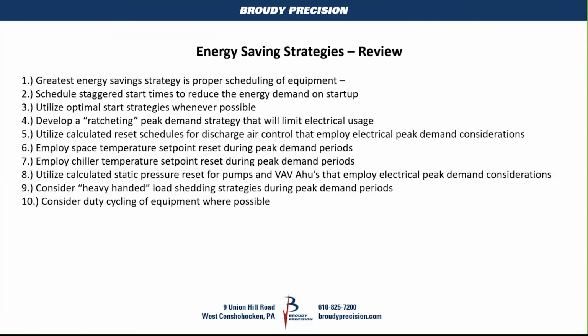We got time left here. So we start shedding loads, or we start changing the set points of air handlers, or we start doing things to reduce the energy consumption to keep it below 10,000. But then after our interval is over with, I want to go back to normal. So that's what I mean when I say ratcheting. It's an analog value. It doesn't stay the same. It's not heavy-handed. I'll tell you a quick story.